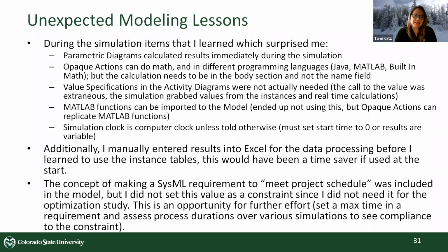I was also surprised to see how much math you can do with opaque actions. I always thought parametric diagrams were for how you did equations. You can use opaque actions, as you saw in some of my other pictures. And you can use different languages. You could actually integrate with MATLAB and have it use a MATLAB language. You can have it Java. There's a built-in math protocol. So you could specify the language and the operation sequence in the opaque actions.